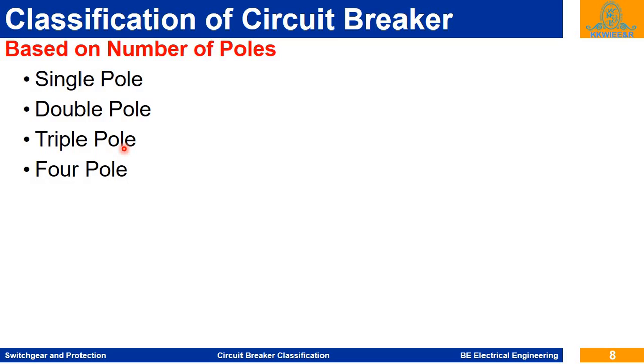Depending on the application, like for changeover of supply from utility to DG or from DG to utility at low voltage level, we have to isolate the neutral connected to the load from the utility when it is connected to the generator, is supplying power to the load.